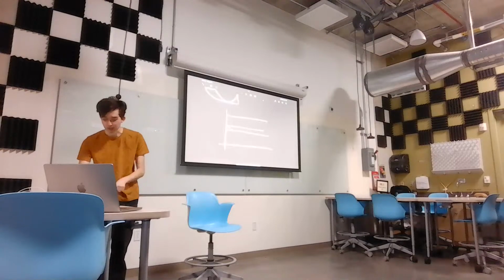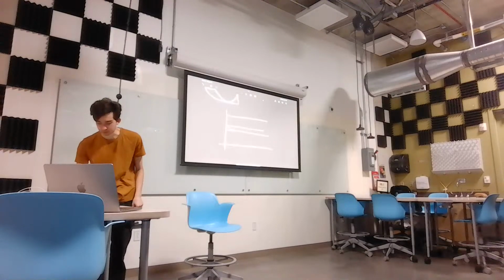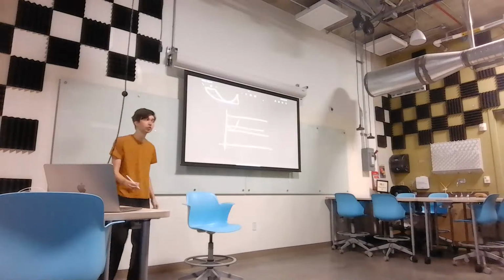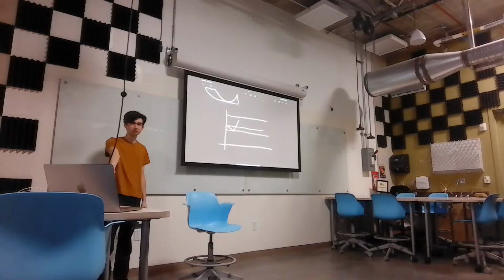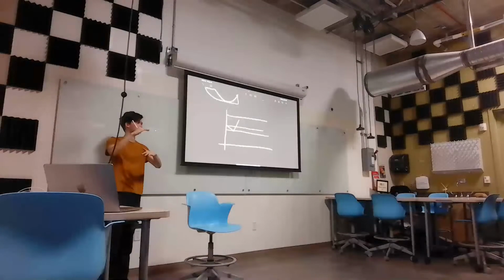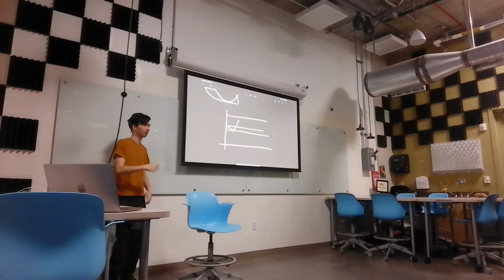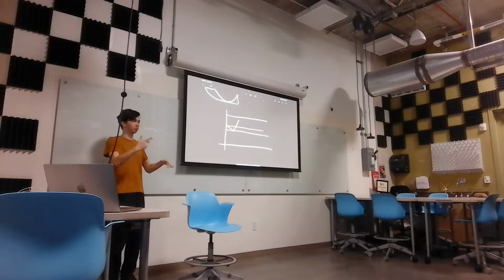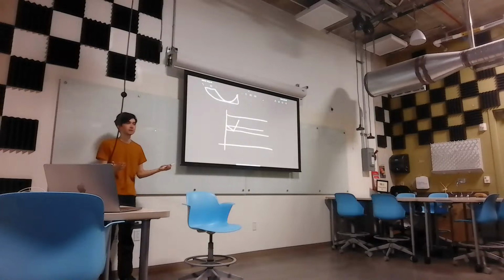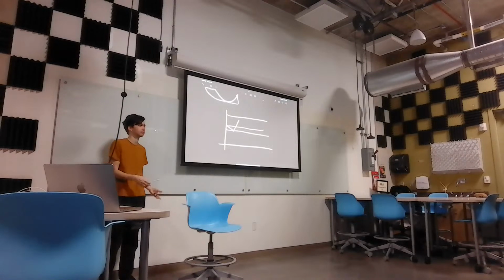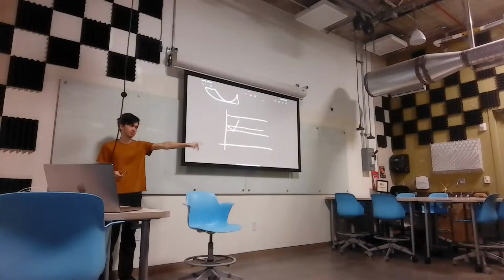And if we were at the top, it would very quickly rise, because the top is much farther away from the target than the bottom. The I term just does this. We set a maximum error, which basically means, okay, the I term is out of error. Oh, it reached a certain error, change the duty cycle. Okay, it's out of error. Oh, it reached a certain error, go back. So the I term will naturally take different amounts of time depending on how far away we are from the target. Did that make sense to you, Carlos?